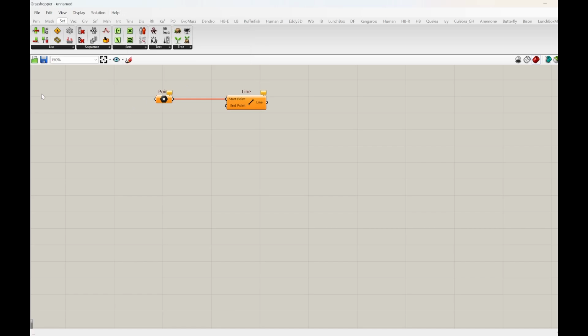So now that we have gone through most of the tabs, the last one that I want to go through is some of these canvas widgets. You have things like opening up a Grasshopper file, saving, zooming, setting a named view or creating a view, making a sketch, changing what the output looks like in Rhino. And then you also have this nifty bar down here where if you type in certain components, it will suggest maybe another component that you'll want to just drag and drop.